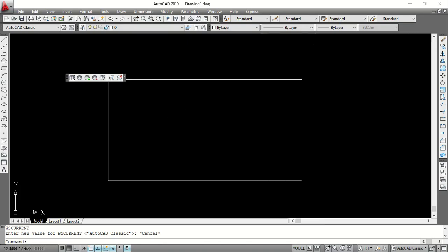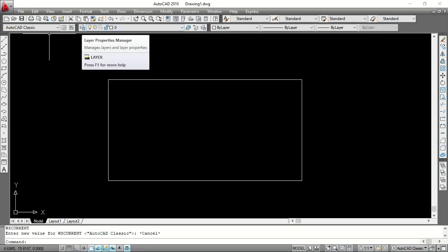Okay, so this is very simple. This is unique. You can see we've touched this. Okay, then we come down here. I've talked about this. This controls your drawing. This is your layer manager, the layer property manager. Let's say you're doing an architectural design, for instance. You want to group the windows in different layers, the doors in different layers, the text in different layers. This you can do, so it's easy to control them from here.